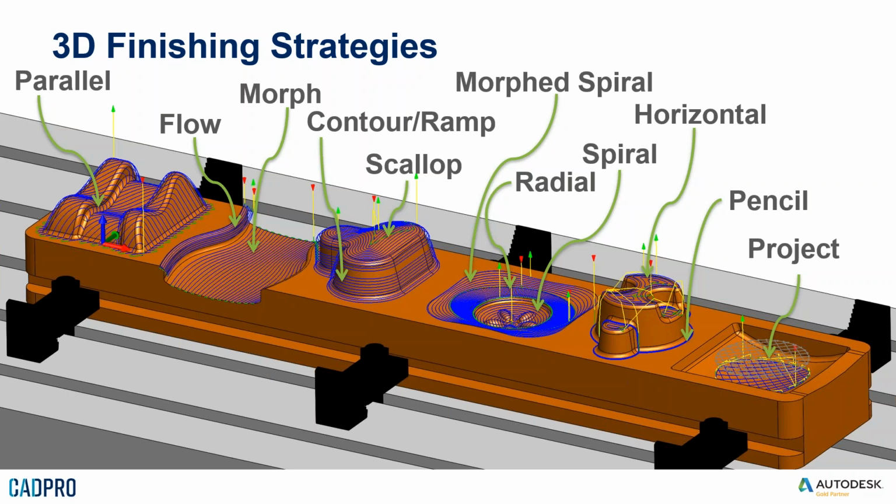But contrast that with a toolpath like Flow, that doesn't use an STL. It actually uses the wireframe with the underlying objects which construct the surface itself to generate the toolpath. So if you've got a really high quality surface, you'll get a really high quality toolpath, and there's no linearization of the geometry from an arc to a series of lines like you'd get with an STL.